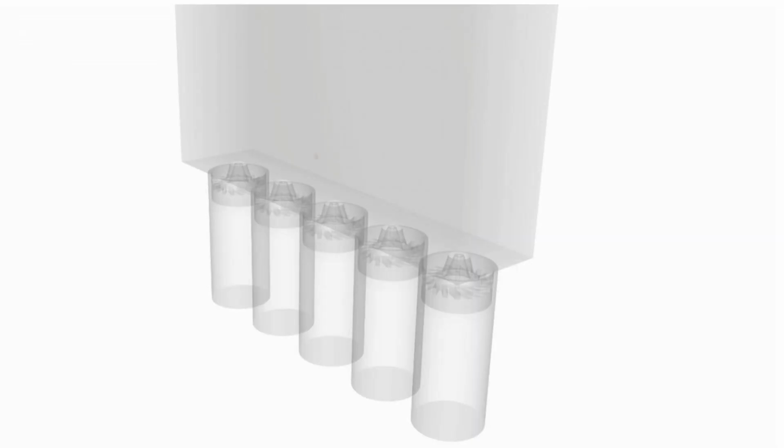We also have another example here of CONVERGE usage. This is an ignition in a gas turbine-like condition. We have 5 gas turbine swirler cups, and we have an ignition kernel right around the second cup. From this animation, you can see the flame kernel establish itself at the second swirler cup, and then slowly propagate from this second cup to the rest of the 5 cups, fully igniting the combustion chamber. And this case is done by my coworker Scott Drennan in the Texas office.